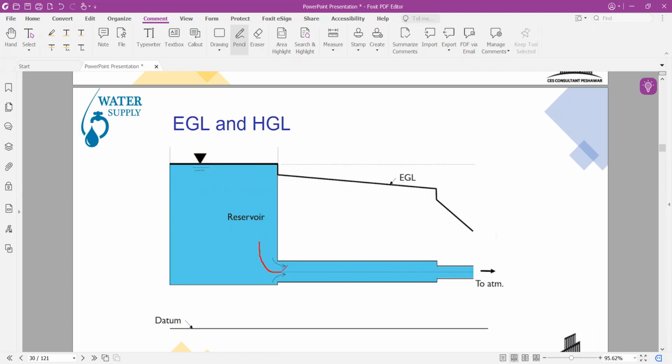Okay, when the fluid flows into this contraction, losses occur. Mainly minor losses occur at that point, and major losses occur when the fluid flows through the pipe, due to the contact of water with the side of the pipe, that is, the friction of the pipe with the fluid. So when fluid flows through this contraction, a minor loss causes a drop in the energy grade line at that point. When the fluid flows through the pipe, due to the major losses from friction, the energy grade line decreases linearly with respect to the losses as the fluid flows through this pipe.